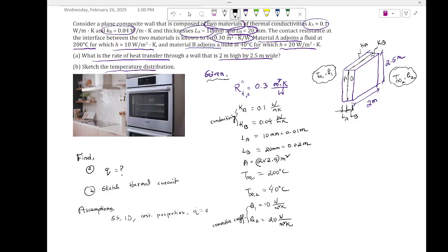Can you draw the thermal circuit, all of you, based on the last class knowledge? I'd like to see that you can draw the thermal circuit where you have all five resistors, and put as much info as you can on it. Try to put the temperatures. Try to put the thermal resistance. For the solids and for convection, you do know the thermal resistance. Remember, for convection it is 1 over hA, and for conduction it is L over kA. So try to put that, okay?